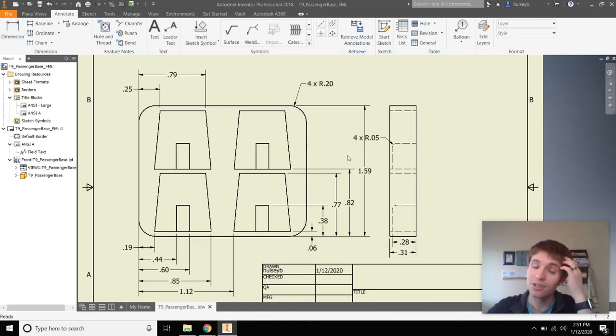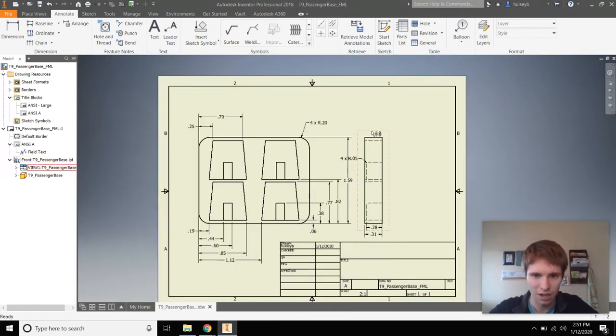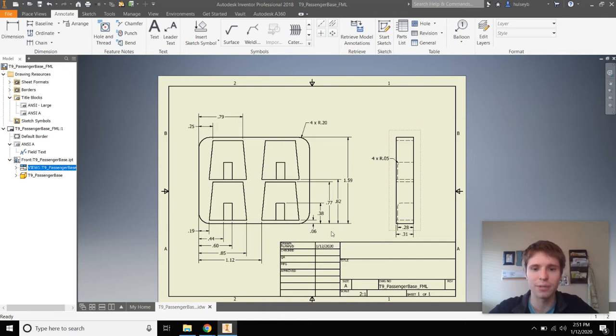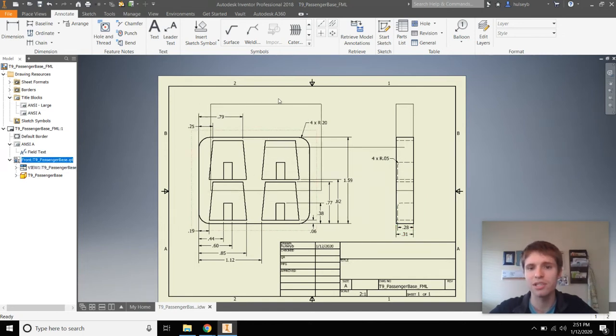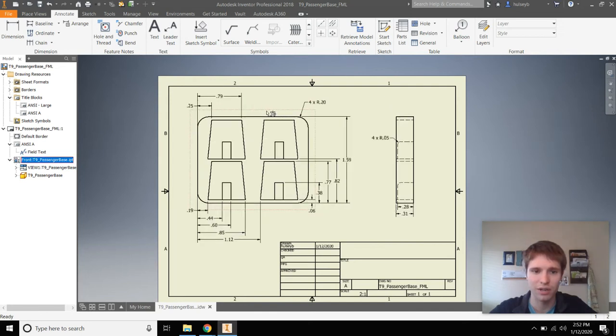It's kind of mean. So then we have some overlap here because we didn't create enough space. All I want to do now is drag this out. And now we want to add some general text, some global notes, but we didn't leave very much room. It's okay, we can click and drag this base view, and you can see since they need to be lined up, it'll actually click and drag the right view as well. So we've got enough space for our text.